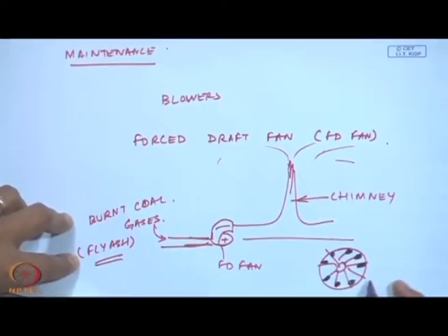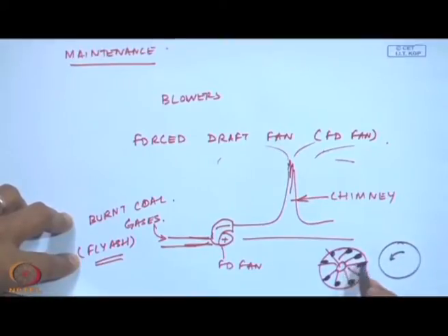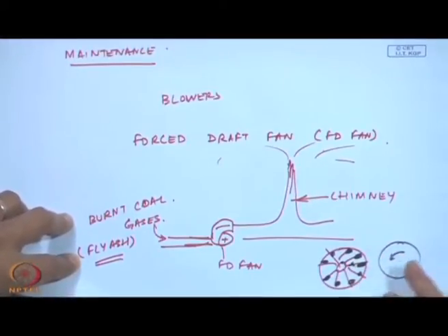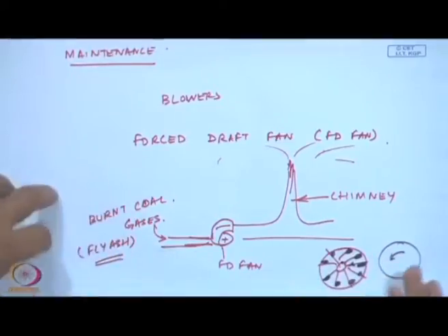And once they stick, they may not stick uniformly, in some location they may get stuck. This gives rise to a fan which is unbalanced, and I have seen cases wherein these fans failed, the blades sheared off and the bearings got damaged because of this excessive fatigue force, which went unnoticed because things got deposited in the blades.